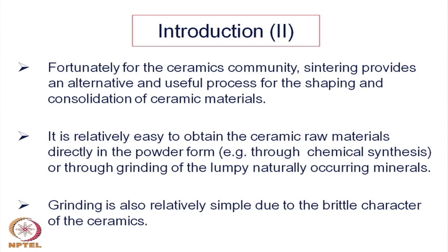The raw materials for ceramics are available in powder form. One of the major reasons is that ceramics is basically a brittle material, and naturally occurring materials are lumpy and can be ground to fineness. At the same time, advanced ceramic products or compositions, as we have discussed earlier, are all synthesized, not naturally occurring, and during synthesis, particularly chemical synthesis, we get powders. So for ceramic materials, the raw materials are basically in powdery form, and because these materials are brittle, even naturally occurring lumpy ores can be ground relatively easily,